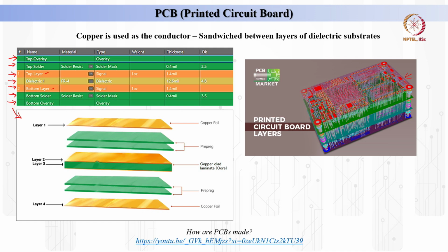Now, above that and below that we use the copper layer. Why do we use an even number of layers? Because it makes it easy for the manufacturer to make even-layer boards instead of odd-layer boards. And here, top and bottom, we have the outer copper layers, and then come the inner copper layers if you are using multiple layers. Let us say this is a 2-layered PCB representation on the top, and here it is a 4-layered PCB. See that there are 4 layers of copper.